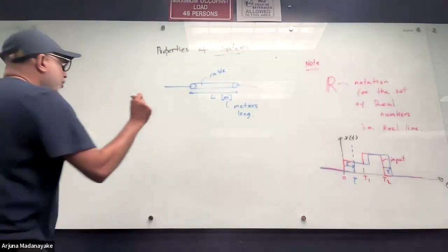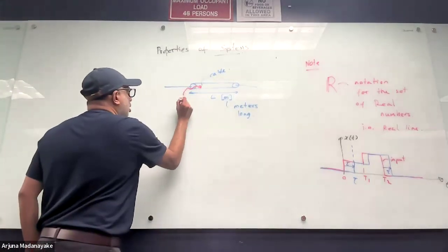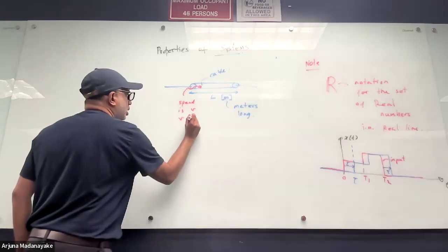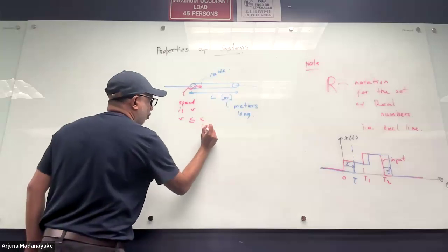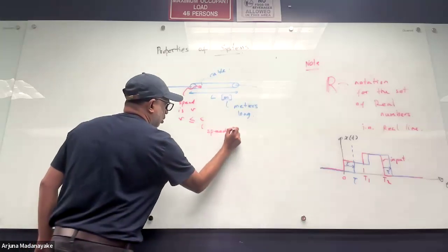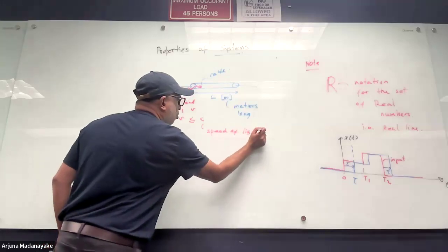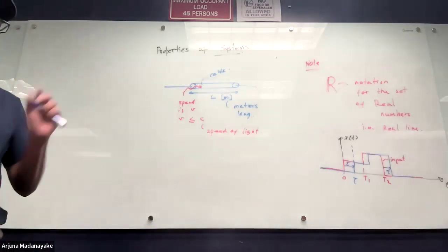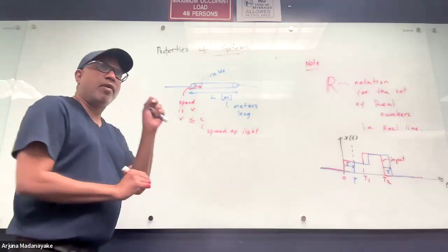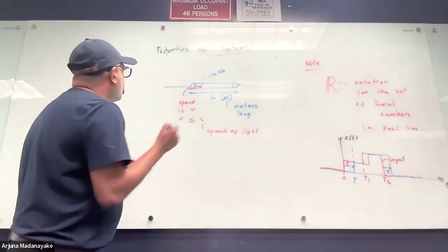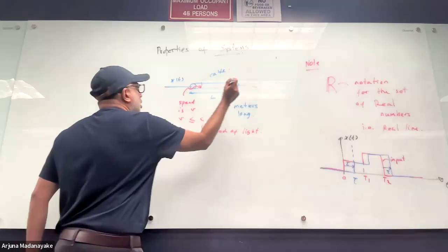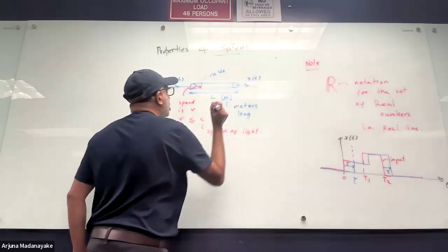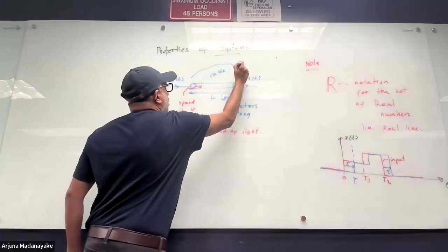Let's say the speed of the signal is V. V is something that is less than the speed of light. It's almost the speed of light, but not quite. It's about 10% slower than the speed of light in vacuum. Very fast, right? These are very, very fast signals. So you put x of t here, and you get y of t out. It's going in, coming out, and it takes tau delay.